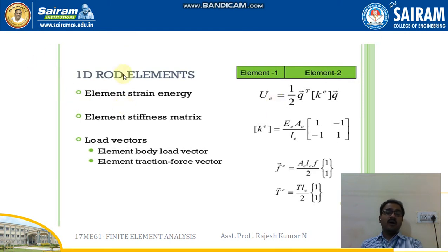Next, along with the previous major important factors, a few more things are there, that is nothing but element strain energy. The element strain energy equation we have already discussed in mechanics of materials and even in design of machine elements. Wherever the strain energy is used, usually it will be used when we calculate the shape function derivation or else the stiffness matrix derivation. The strain energy concept will be used for all the deformed structural components.